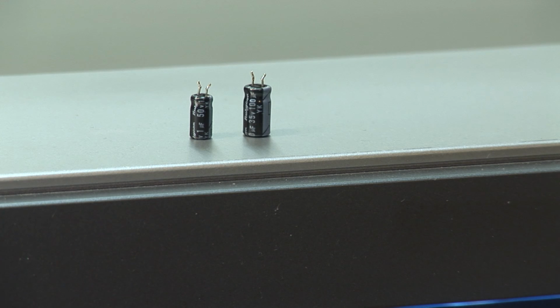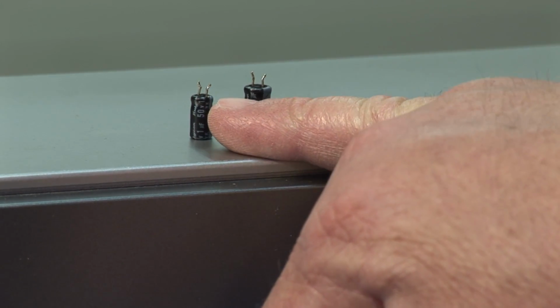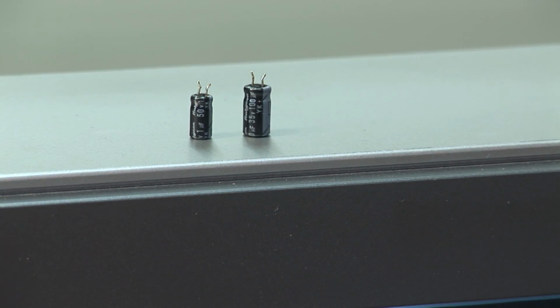And some of the earlier, and when I say earlier, I'm referring to sets made in the late 80s, early 90s, used those red colored capacitors, and they would actually be leaking. The plug on the bottom was all soft and the electrolytic was leaking out of them. And we had to order the original one from Toshiba because a regular capacitor would fail very, very shortly.